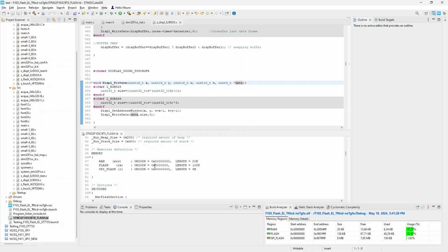Otherwise, the address points to the external flash mapping area. That's if it is a constant array stored on the SPI Flash. In this case, the base address is what we defined in the linker script. In our project, it is 0x9000 0000.